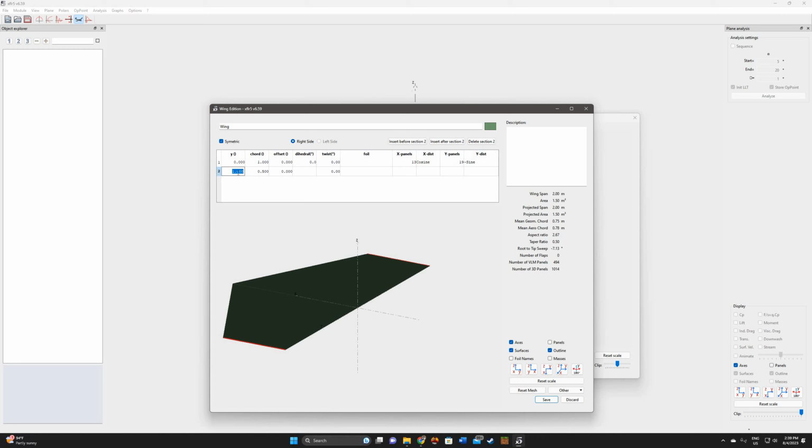So to find the wingspan value, you need 2 things. For a tapered wing, the planform area is going to be the chord length at the root and the chord length at the tip. Add those 2 together, divide by 2, then multiply by the wingspan. And we know the aspect ratio is b squared divided by the planform area. So if you combine those 2 equations, in this case you find that the aspect ratio is equal to the wingspan over 0.75.